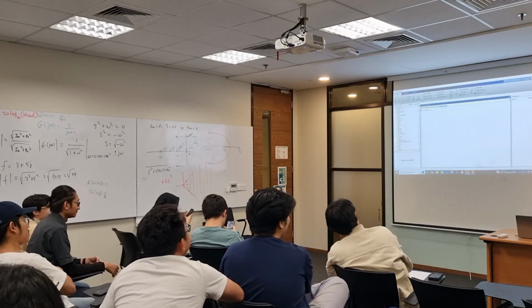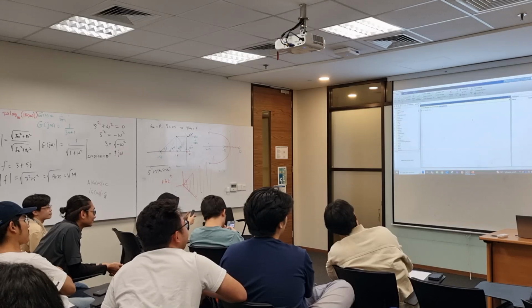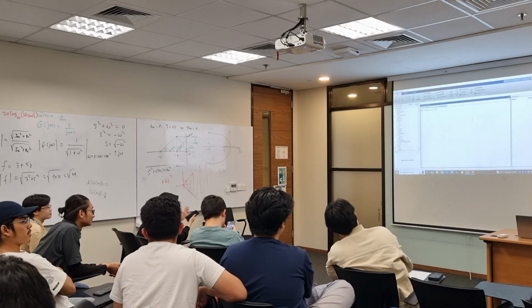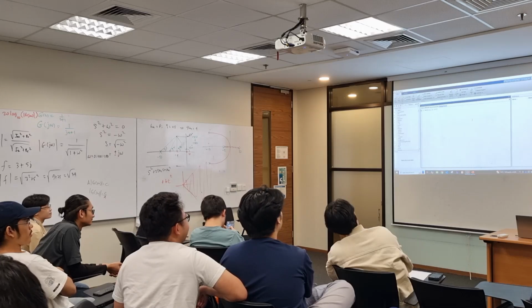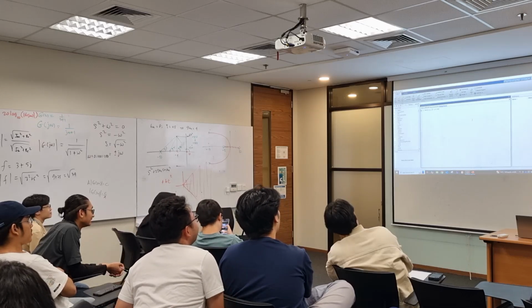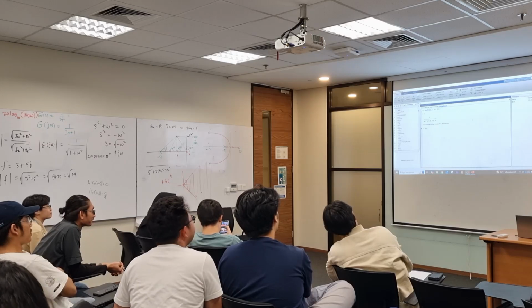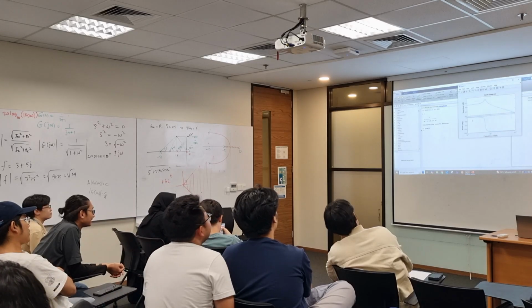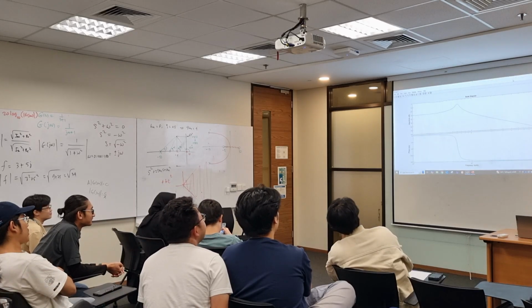What kind of second order system do you think of? S squared plus 0.6 S plus 436. Damping ratio is so small, eh? Okay, then you write down the Bode plot of G. Yeah, I mean, that is a peak.